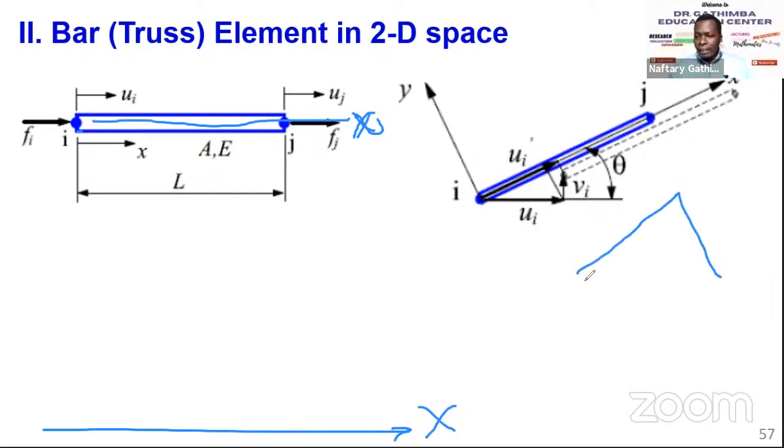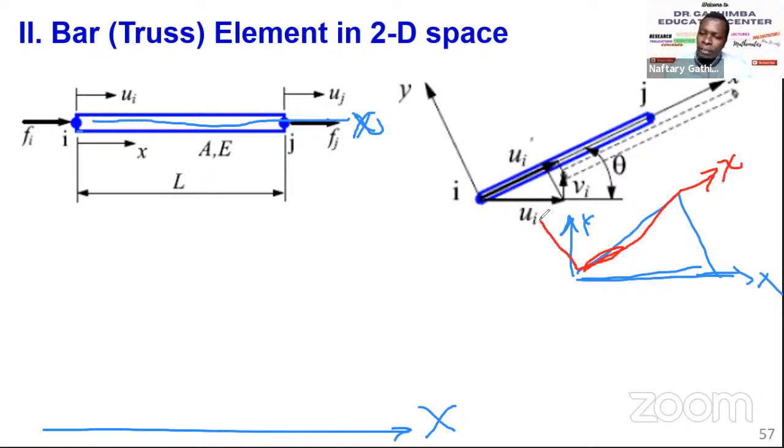So if we have our truss here, we have the Y direction there, and the X direction. Okay. So this is the global coordinate system, or the overall, which represents the structure. But when we come to this element, we are saying the horizontal orientation of this element 1 is the horizontal direction. So that will be small letter x. And then, of course, its vertical is orthogonal. Remember to keep the angles perpendicular. So the small y for this element 1 is in that direction.